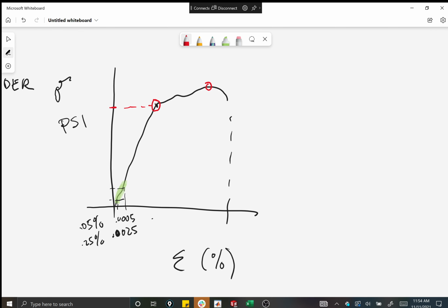So you're changing the material at this point. There's other ways you can change it. You can heat it up to anneal it. There's all sorts of things you can do. But it actually can take more stress past the proportional limit. So obviously the slope's going to be much lower. And then it gets to a point where that's the most it can take. That's the UTS. I'll just say Y here.